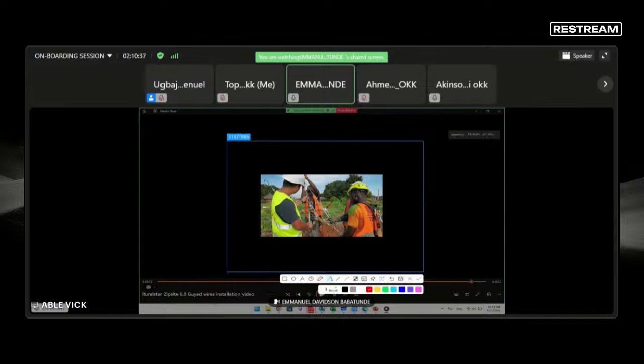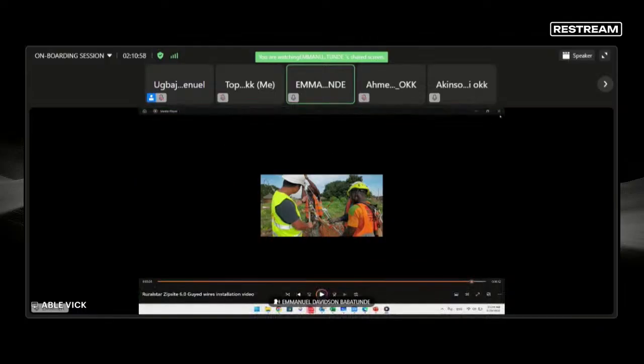This remaining part at the bottom is for future maintenance. In case in future the wires become slack, maybe after 10 years, the maintenance team can go with their spanner and adjust this bolt down, and this thing can drop down and give the wire some little tension again. So your tension should be at the tip. Leave it at the top here. Don't adjust it down anymore. So with this, I'm sure you understand.